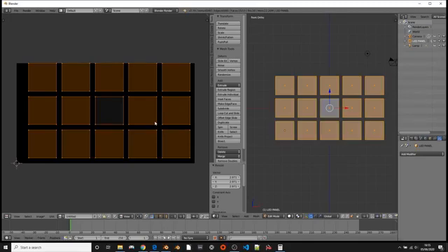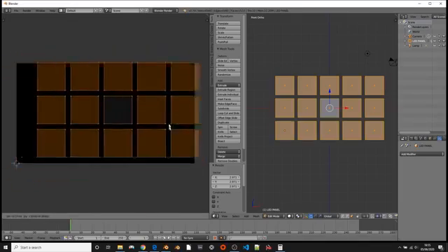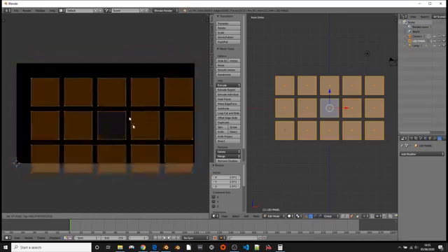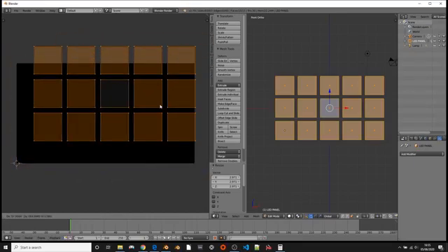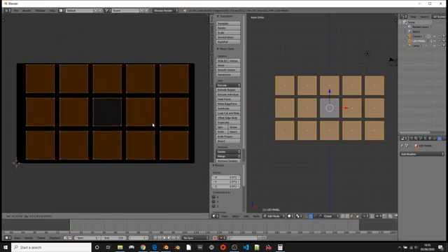So to translate, we press G. Maybe think of it as G for grab. So let's just press G. If you remember the rotation, it's a bit like the rotation. When I just press G, I can move it everywhere. So I could sort of get it roughly in there actually, if I'm totally honest.